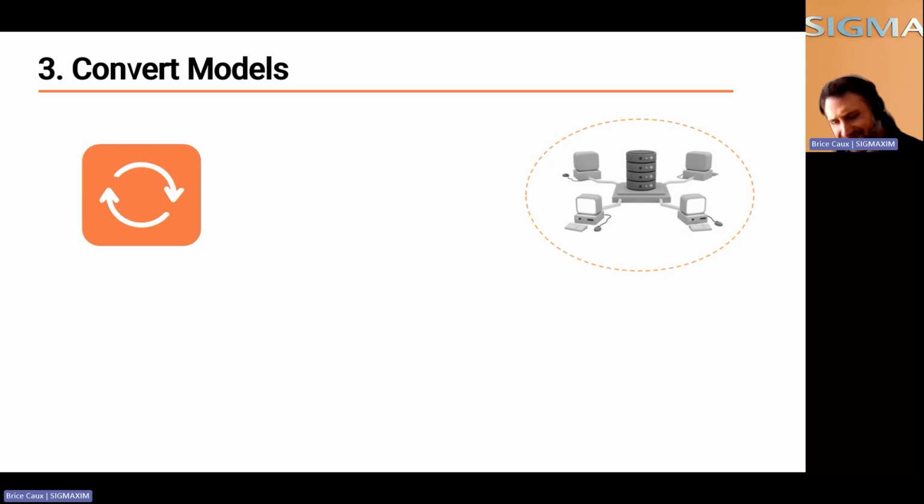For example, in this process, I have an assembly and I want to create sheet metal parts because I need at the end to get 2D drawings for sheet metal parts with a flat view, with an export in DXF scale 1, and maybe create some reports to prepare the production, the manufacture. If you have only one or two models, okay, you can do it manually, but imagine if you have 1,000 components, it's not the same story.